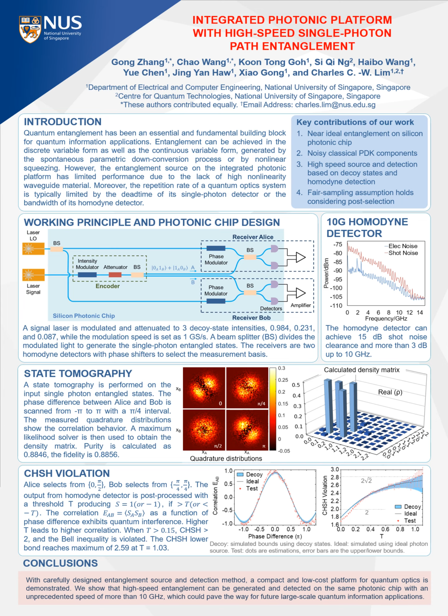The receiver uses a shot noise limited homodyne detector. The output signals are subtracted directly on chip and then amplified using off-chip RF amplifiers. The output results are collected using oscilloscopes. In our scheme, we treat each time sample from the oscilloscope as one quantum state. Thus, a higher-speed detector may push the repetition rate higher.